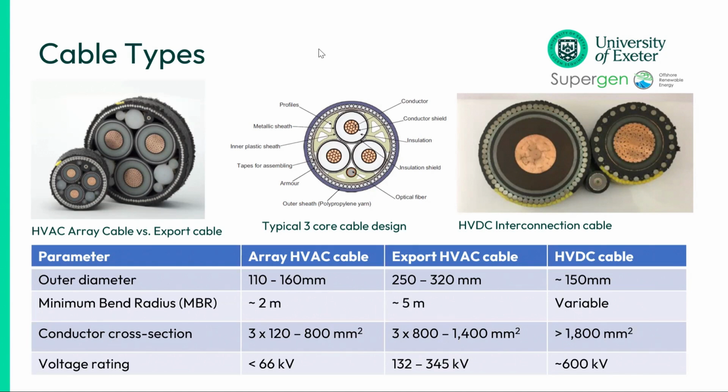Yeah, all of those. It depends a little bit on the phase. Lots of things went wrong in the early days of installation, and that's largely exceeding minimum bending radius or exceeding axial tensions during the pull-in. VIV is more an issue, I think, when we go to deeper waters and very stiff cables.